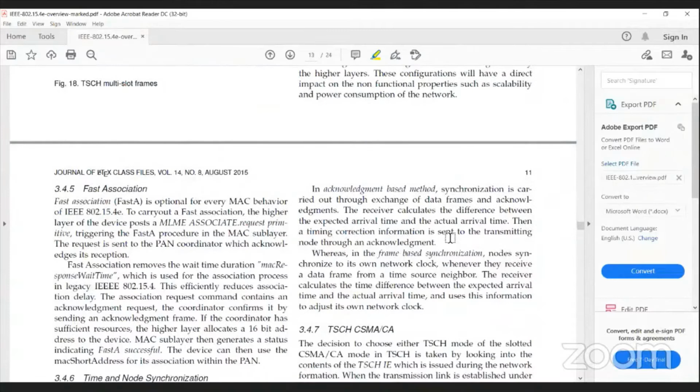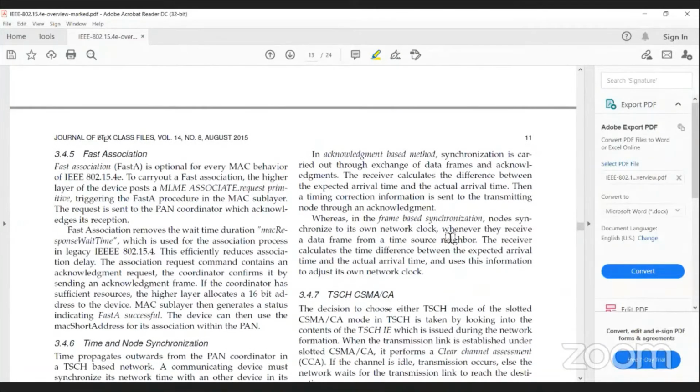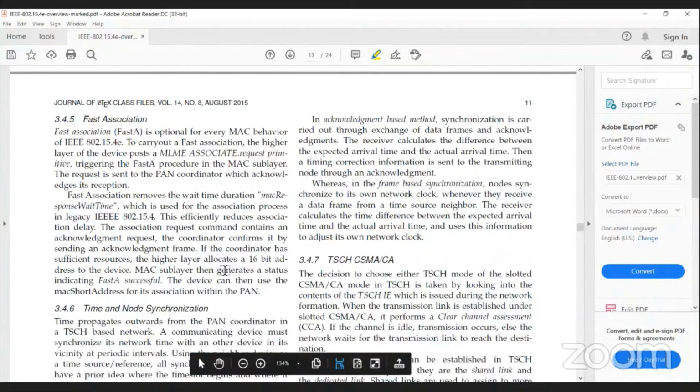Fast association I mentioned to you is very critical. See, one of the things you can do is, as Ipsita mentioned, there are 16 channels. You don't need to use all of them. Why should you go for all 16? Keep it 4, keep it 5. Now that is your choice as an administrator who sets up the network. So keep it at a reasonable number so that your slot frame and structure is designed well for the current network, plus a few additions that may come up in the coming months or coming years. So all that you should also make sure.